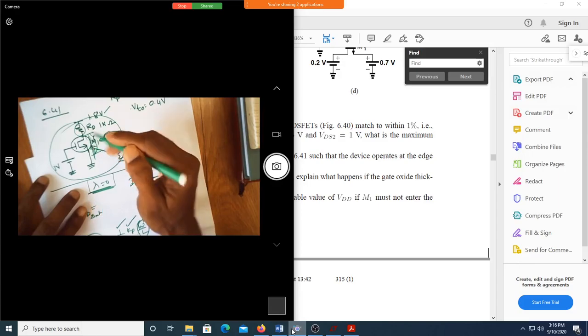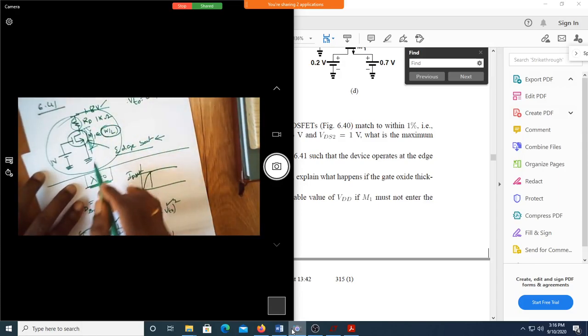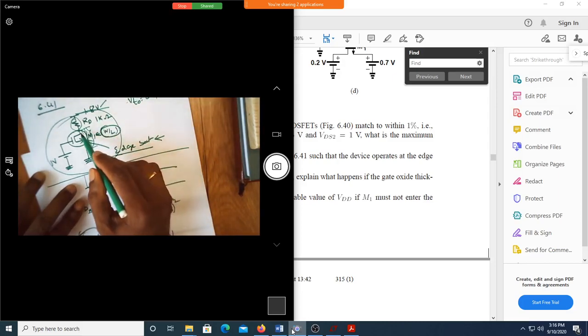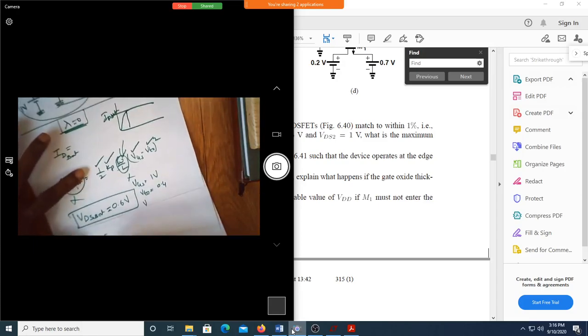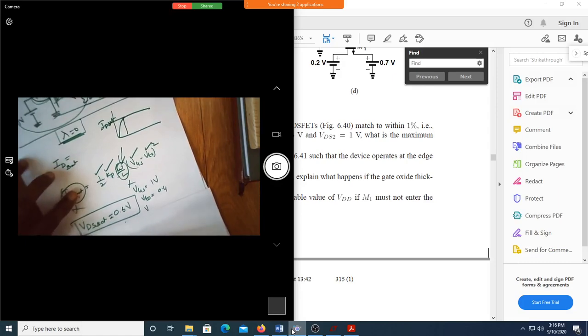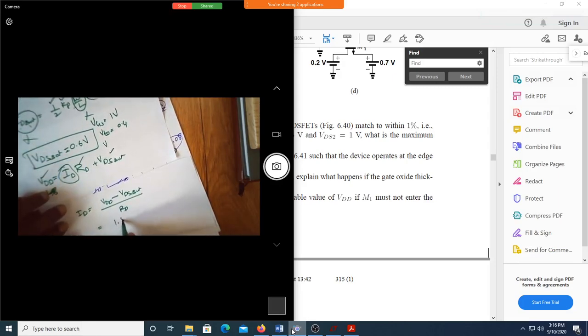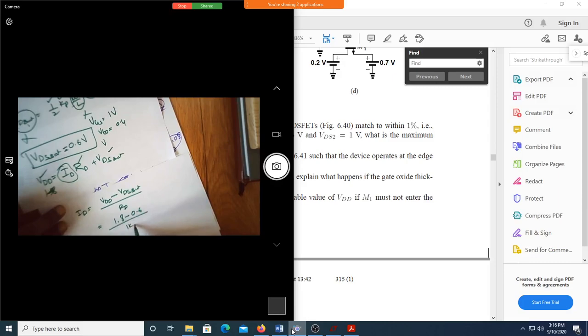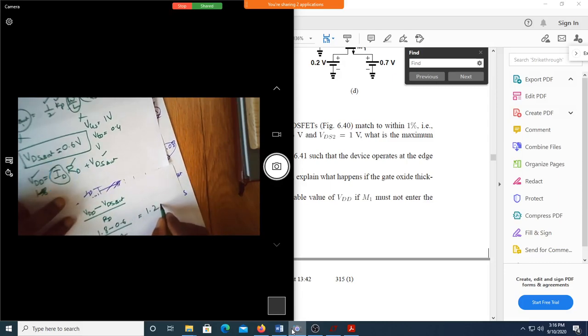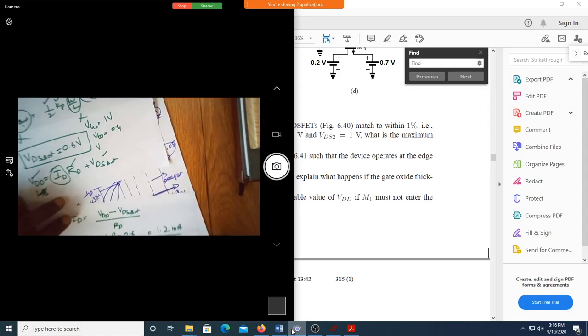See, here you got 1.8 volt. Out of 1.8, if you want to keep this at verge of saturation, required voltage is 0.6. How much is the remaining voltage that should drop across RD? 1.2. So shall I write, using this expression, ID is equal to VDD minus VDS sat by RD, which is equal to 1.8 minus 0.6 by 1 kilo ohm, which is equal to 1.2 milliamperes. Am I correct?